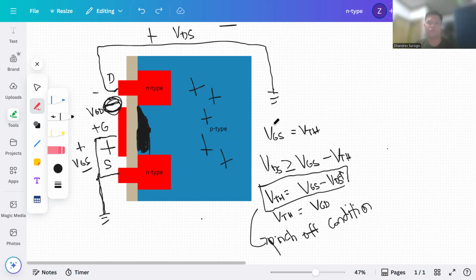So here, we can see that as we increase the VDS value, the effective length of our channel changes. We can say this measurement is L, and the length that was cut off, let that be delta L, or the change in L. As the drain to source voltage increases, the delta L lost from our channel length also increases.